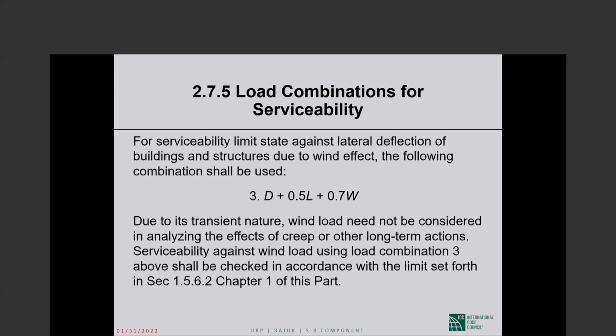The only time gravity loads will cause lateral deflections that will be additive to the deflections caused by wind is if you have a very distinct lack of symmetry in your structure. In a symmetrical or near symmetrical structure, dead and live loads will not cause any appreciable lateral deflections.